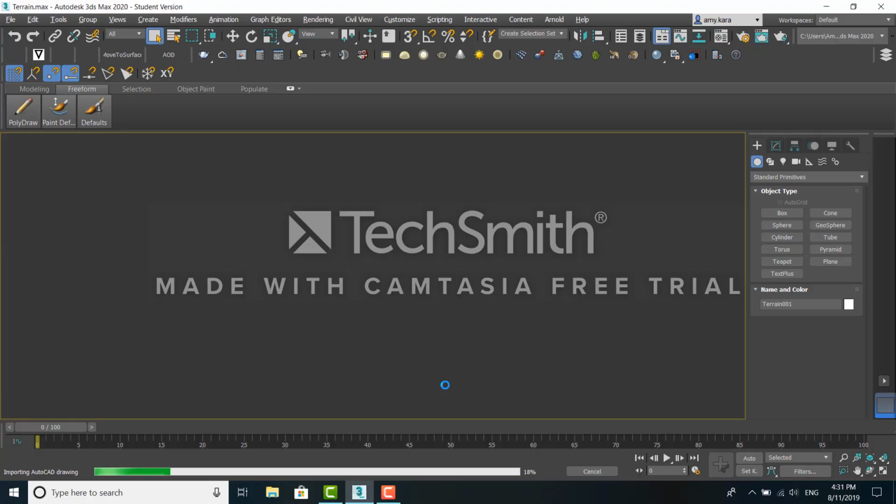As this is taking quite a long time to import actually, in order for just this tutorial and also for your sanity, I suggest that you import sections of the FIGUREGROUND in so you can have smaller areas to import into 3ds Max, making it a bit easier to import and then play around with that DXF. So I'm just going to cancel the import.